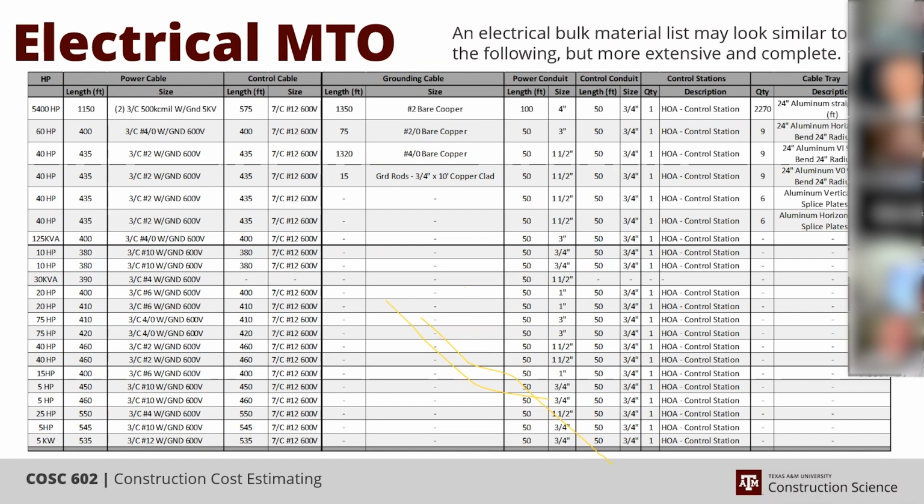And then that grid itself, even though it's buried in the ground and could be grounded in and of itself, there are rods spread out throughout the grid that are usually somewhere in the neighborhood of 10 feet long, as shown here. And it's showing it's a 3/4 inch diameter. They're driven in the ground to a point where they're not seen anymore, and they're taking that current deep into the earth. So if there's a short or whatever, then that is what's going to direct it away from everything else and take it to the ground.